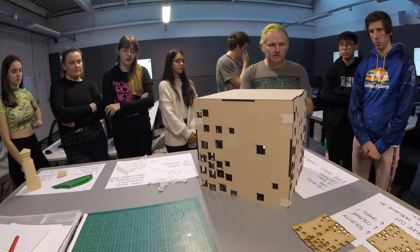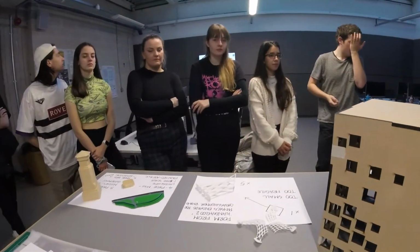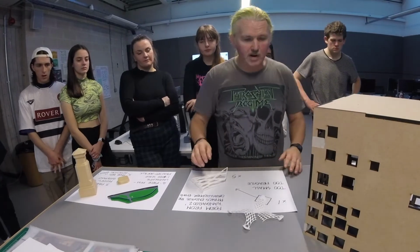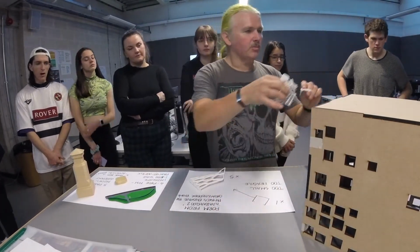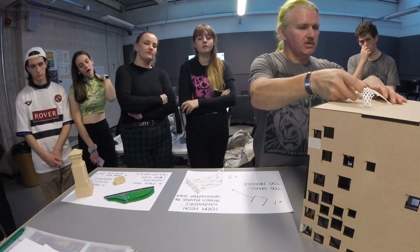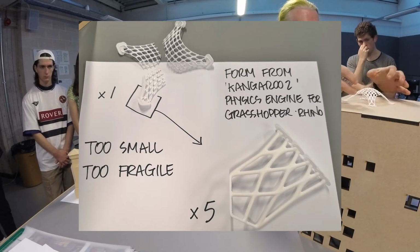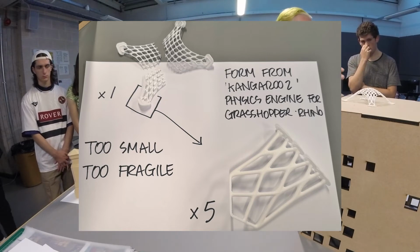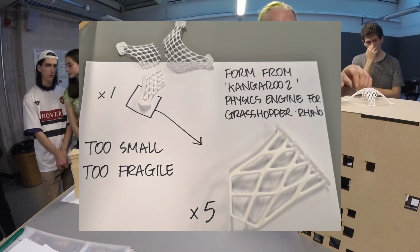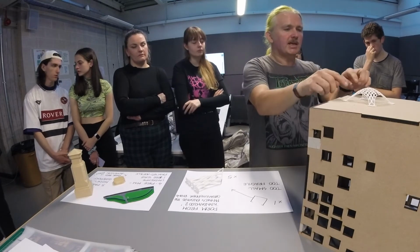Okay, so, staying with the scale kind of thing, I think I've covered all the points there. Got some stuff here that's looking at scale, and quite fortuitously, this got broken on the way here. So it was a little tensile structure model. This is from Grasshopper. There's a feature in the software called Kangaroo, and it lets you generate nets and tensile structures. You tell it where it's going to be fixed down, and you tell it how much force you want to apply on it. So this is an upwards force, and you tell it how elastic you want the components to be.